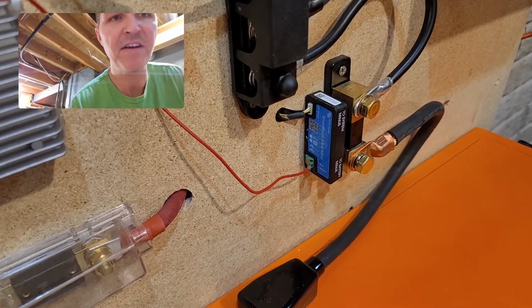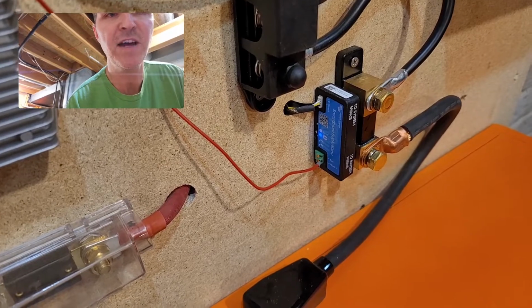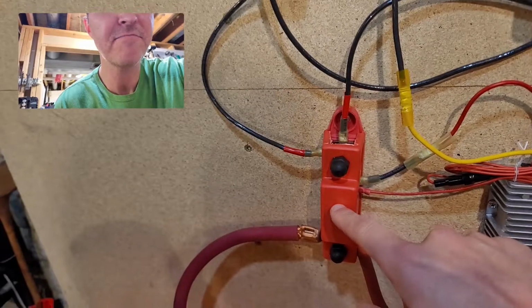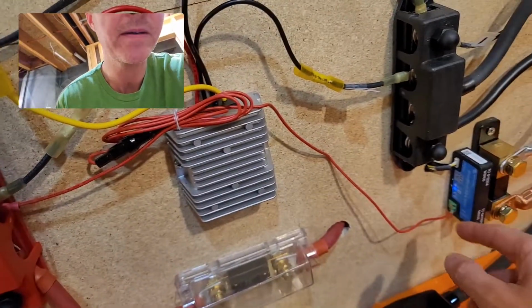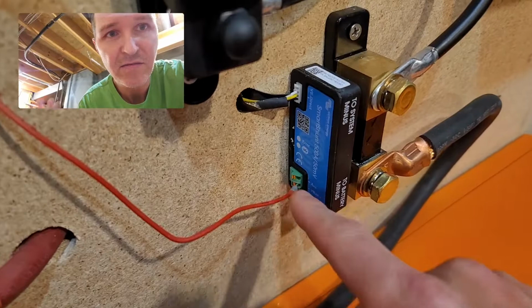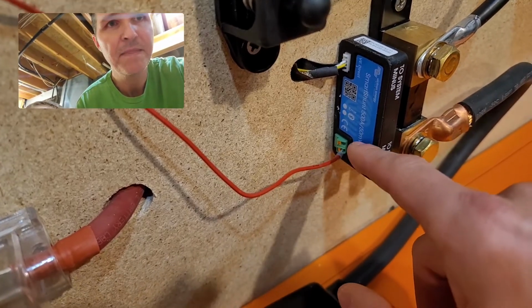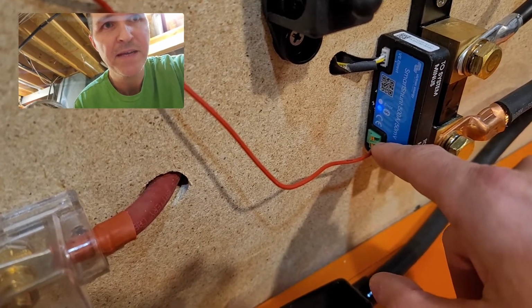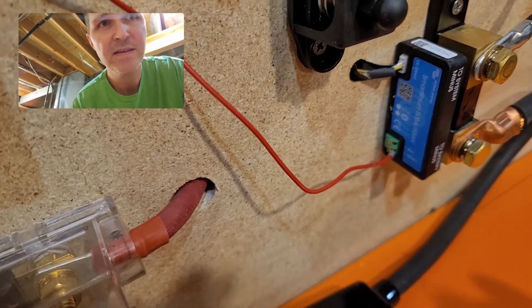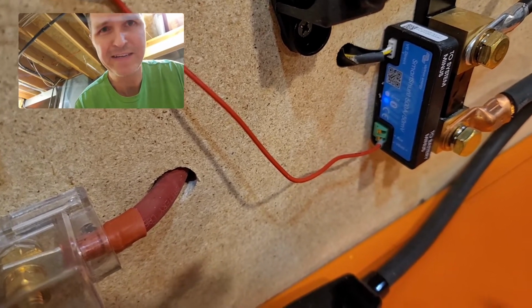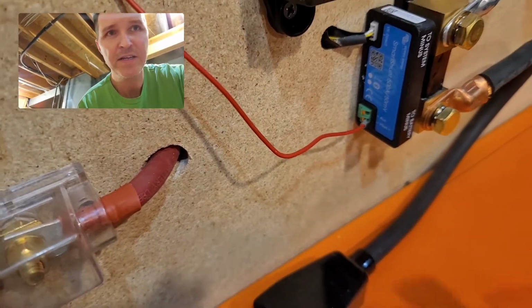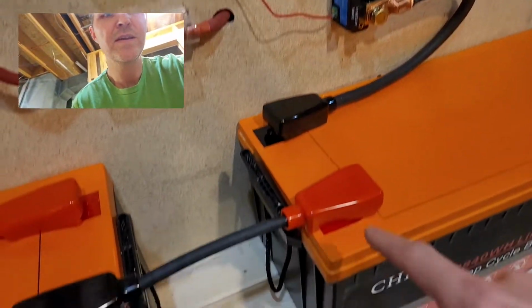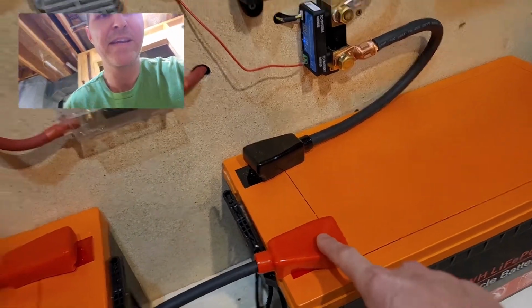This is a 500 amp smart shunt from Victron, and right now I have one cable that goes to my positive bus bar, and that is just giving it power. But as you can see right here, there is an auxiliary port as well, and this auxiliary port can be programmed to be a midpoint voltage deviation reader, I guess you could say. So we're going to connect a wire going from that secondary port to this battery right here.